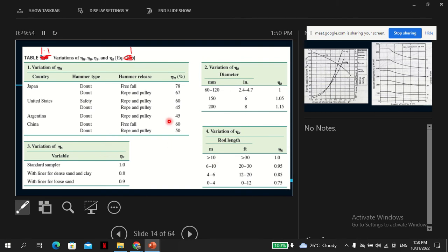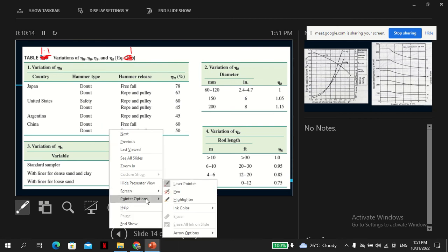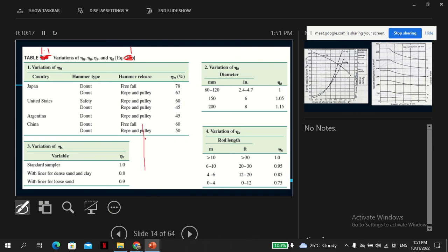Yes, this also has something, because you remember in theory we are saying the stress would be the unit weight times the depth z, while in reality the stress reaches a point and remains constant.